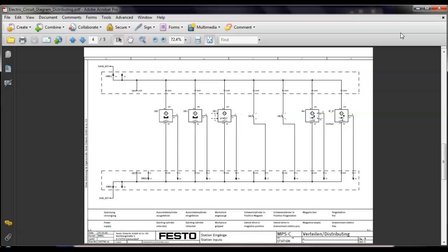Because you've got the part number for the sensor, make sure you look up that part number. Don't just go to that company and buy a sensor. Odds are they make it in both sinking and sourcing models. Like when you buy a car, it might come in 2 different colors. You want white or black, but it's the same type of car.